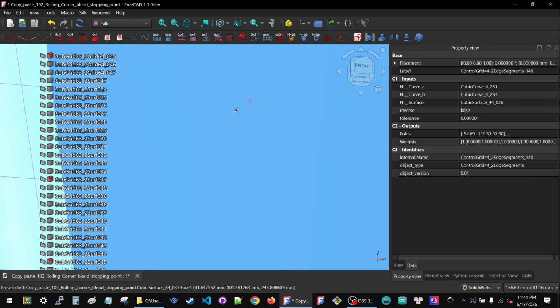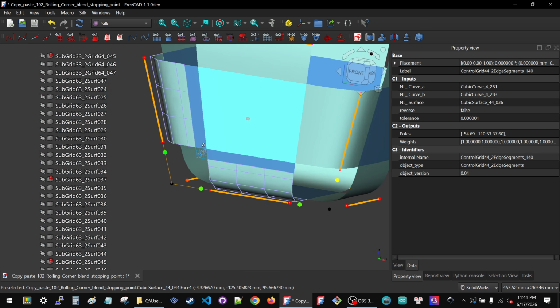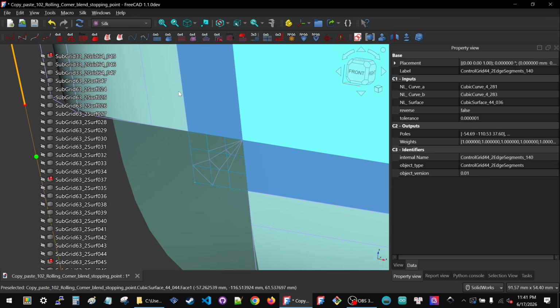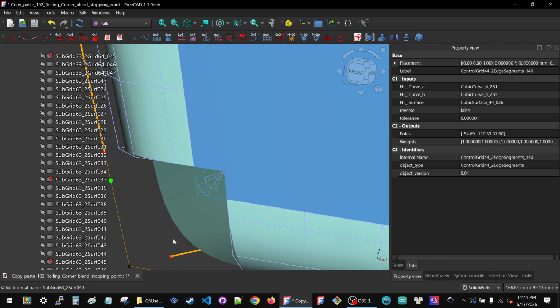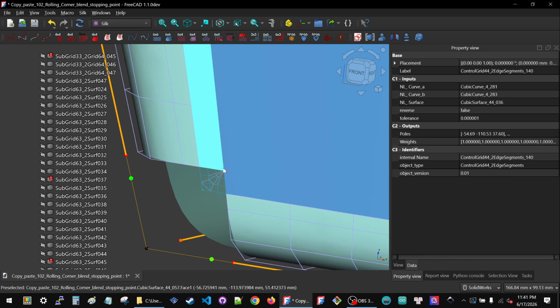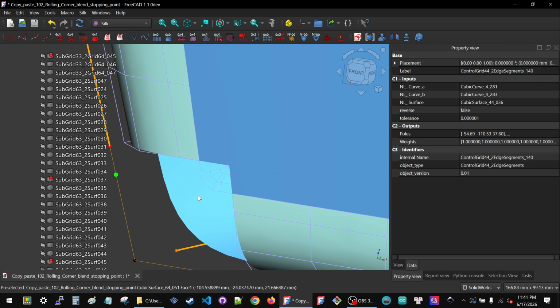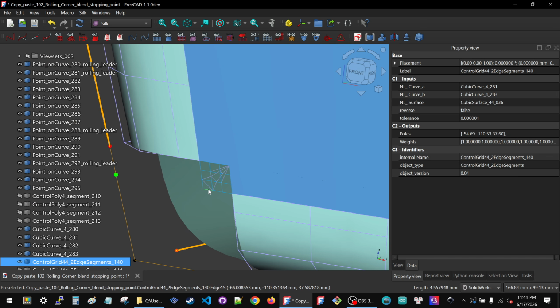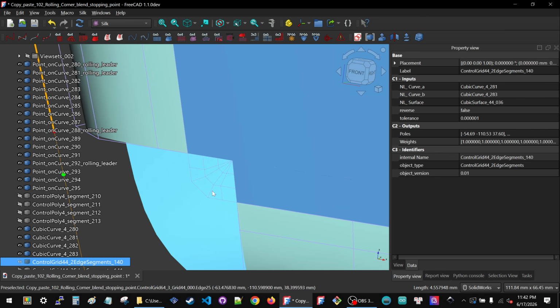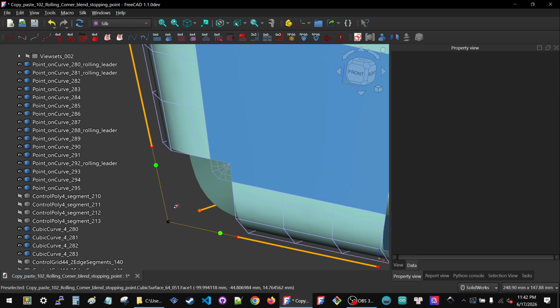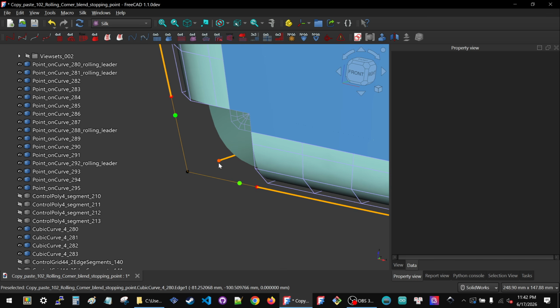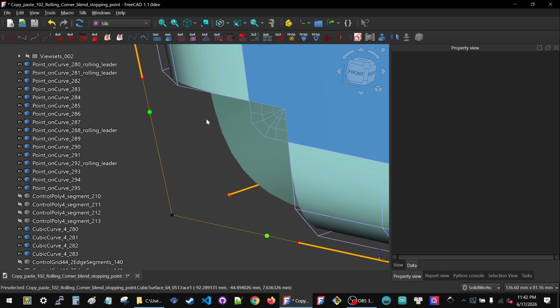It's hard to see with the color that it uses, so I'm going to rotate myself here. See, in purple, you can see an overlay that does a spider web kind of thing in here. I still have the original grid selected, so I hide it. But if you had clicked off for some reason, just select the square grid and hide it. This is the corner rounding grid. It does not produce a high quality surface, but it is a scaffolding piece.